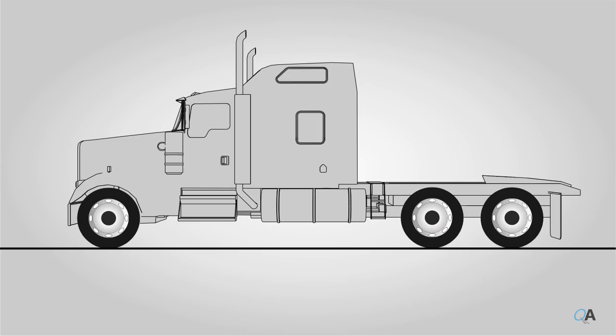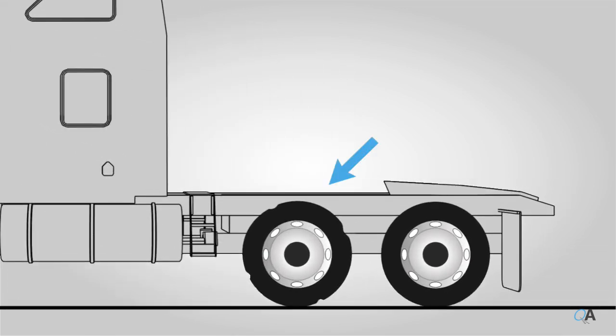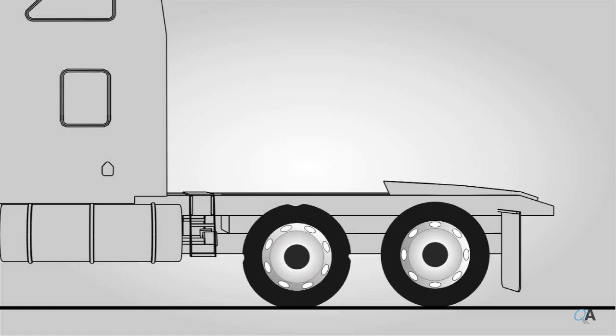An out-of-balance wheel tends to produce cupping and flat spots as the wheel vibrates. The eccentric movement of the wheel increases and decreases the load on the tire in a consistent pattern, which causes the tread to experience localized wear at high load points.